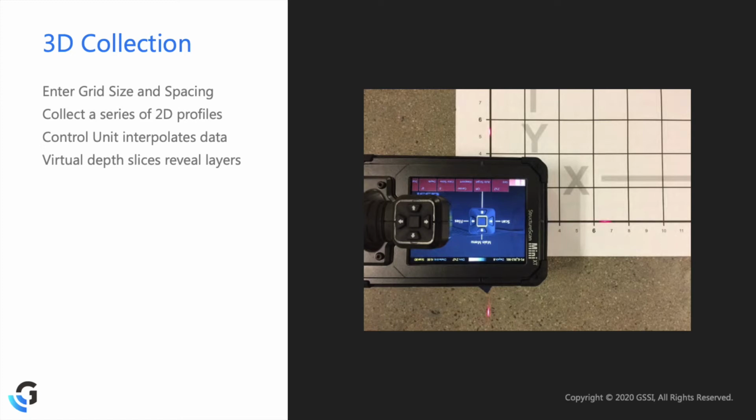If you create your own grid, it must be one of the 4 preset sizes, and the grid lines must be 2 inches apart. So simply tape your scan template securely to the concrete. If you're using the GSSI pad, mark the concrete holes in the corners. This will make it easier to draw objects on the concrete during interpolation.